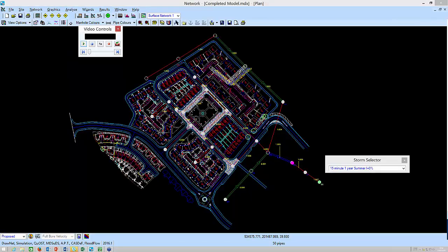And I've run the analysis to check it. So here it's the same model, but I just completed it. We've got the 2 swales here, 2 swales here, feeding into the pond, and then I've got the porous car park that's replaced pipe 4.001.